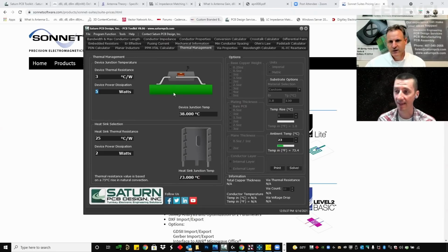I'm thinking, because in a datasheet, for example for regulators, they will give you this junction and some other parameters, but you still need to calculate the area you need to take out all this heat. Well, yeah, and this isn't going to tell you all of it.